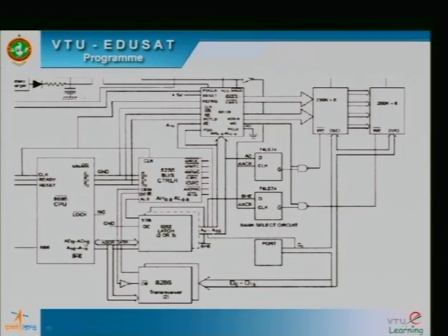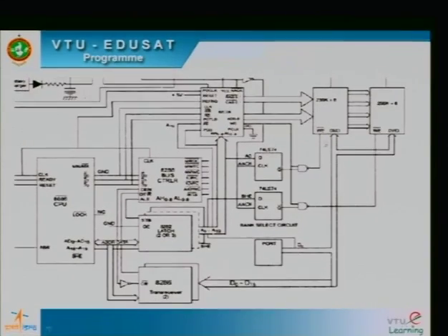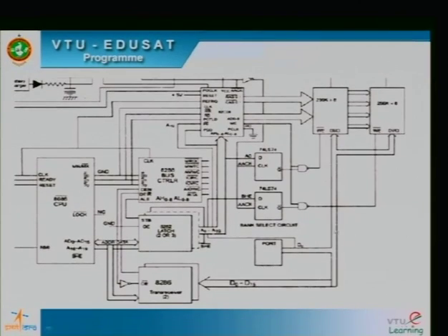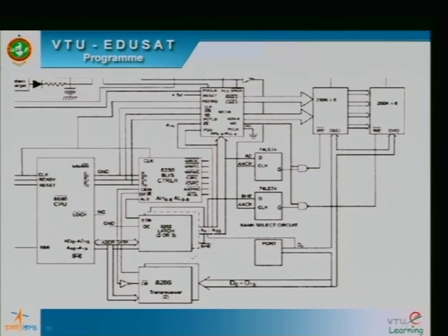So you put the address on the address lines, it has to go through the latches and the decoding circuitry, and come to the memory. The memory, once it is enabled, requires some time, that is an access time, and after the access time it will put the data on the bus. And again the data has to go back. This portion is your path delay and this portion is your memory access delay. So by the time the address is there and the data is present here, some delay is present.